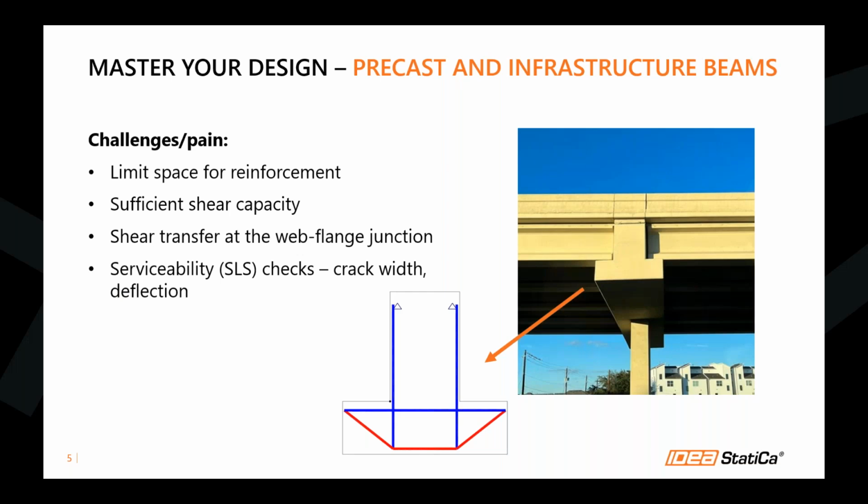One of the most commonly used methods for dealing with such structures is definitely strut and tie, which is perfectly fine. It's proven by time. However, it has some disadvantages. You have to know how to build the equivalent truss model. The process can become quite iterative, maybe even time-consuming. And most importantly, this method doesn't describe serviceability limit state checks, for example the crack width check or deflection check, which are really crucial for this type of structure.